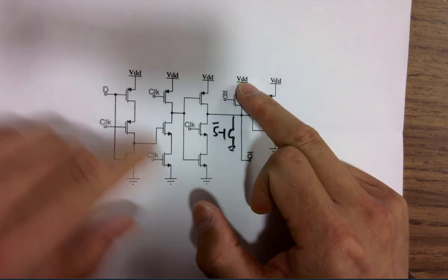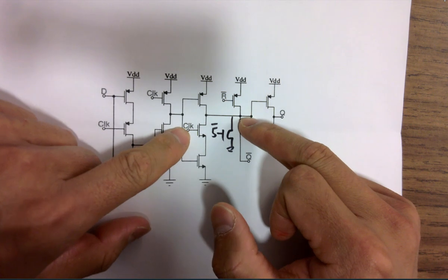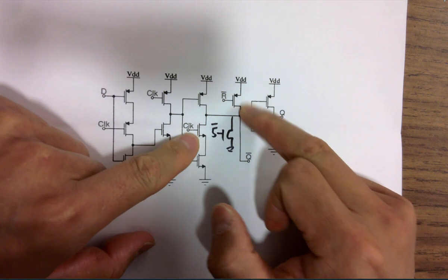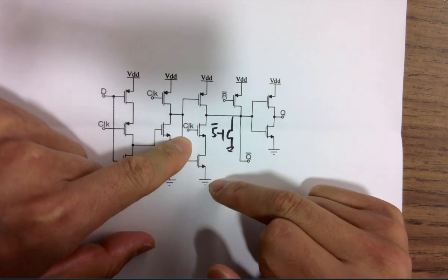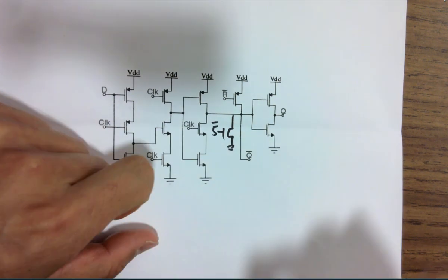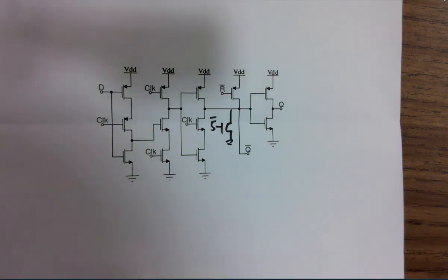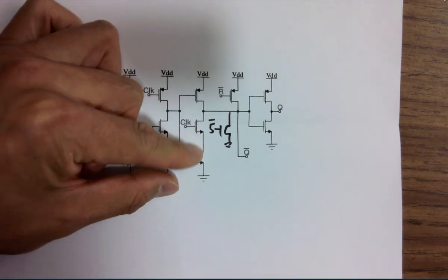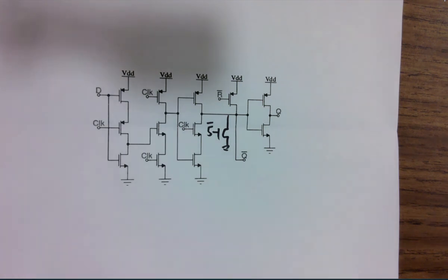So if you are resetting, but just during that time frame, clock is on, this is on, what's gonna happen? Shorted. Yeah, it's actually shorting this guy to ground. So in that case, what can I do? But this is still resetting it. If you still want to reset it, I mean, there will be some channel resistance. It won't really be shorting it, but it's probably more about competing, right? One is pulling down to ground, one is pulling up to VDD, which is stronger? But you still want to reset it, right?